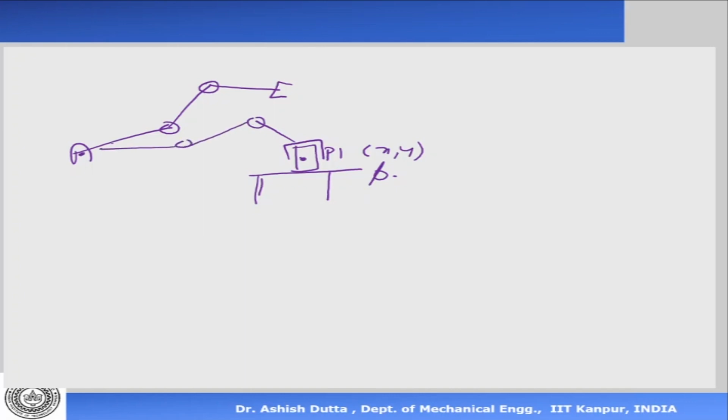Now to be able to do that, I'm going to give you x, y, and phi. Now you tell me what is theta 1, theta 2, and theta 3. This is called the inverse kinematics problem, the inverse of that. This is of course more useful because when a robot has to move in space, we are interested in the position and orientation of the end effector.